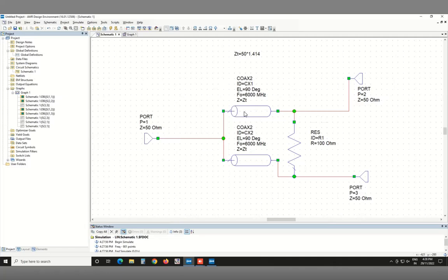That will allow you to push the bandwidth more. So in a practical or commercial device which uses Wilkinson techniques, you might have multiple sections of these things to give you a very broadband kind of performance. But I think the ones I showed you, from this company called Mini Circuits, probably don't have too many sections.